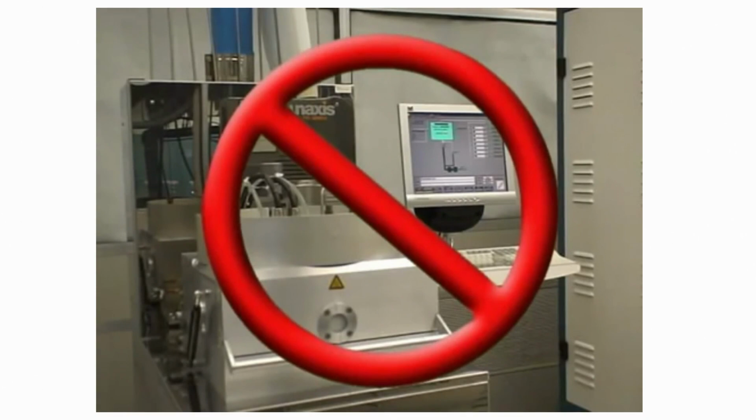Do not leave tex wipes or any other item or material that could possibly melt inside the chamber. When heated, materials such as plastic are prone to melt and leave behind residue, which could in turn lead to contamination issues inside the chamber. Therefore, it is imperative that any tools you may wish to use, such as tweezers, not be made of anything other than metal. You should never use any kind of chemical inside the chamber as well. It is possible for them to ignite and/or produce dangerous fumes if they are heated.